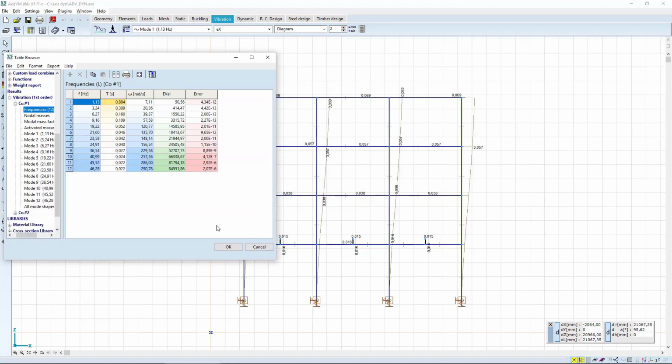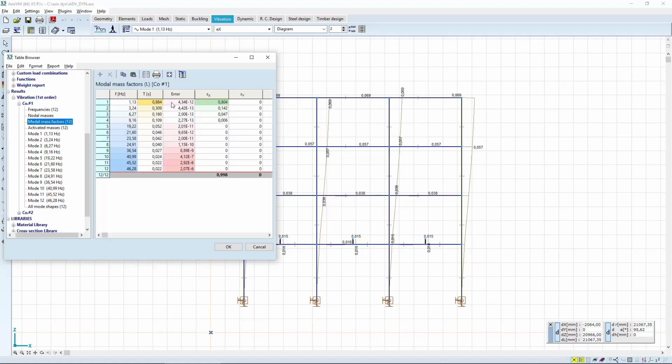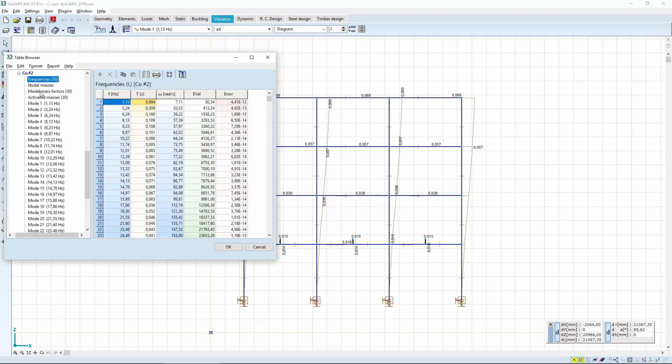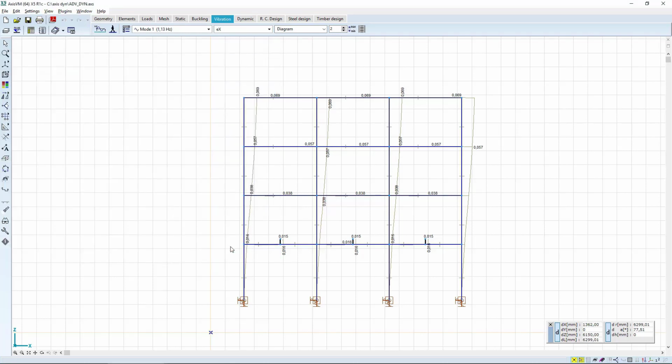In a time history analysis, the factors for the Rayleigh damping have to be set based on the main dominant frequencies. The constants will be tuned by considering a range of frequencies. The boundary values are the following in our cases. Based on the first analysis, the lowest frequency is 1.12 Hz and the maximum is 9.09 Hz. In the second analysis, the lowest frequency is the same and the maximum is 9.2 Hz.